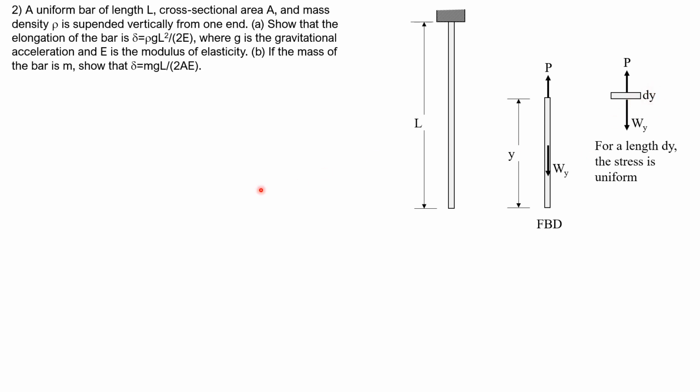So let's begin with the differential deflection formula. Originally PL over AE, it will now be equal to P dy over AE. AE is constant for this situation.